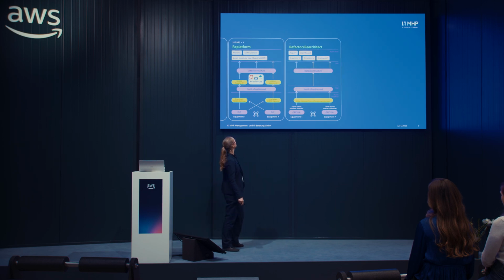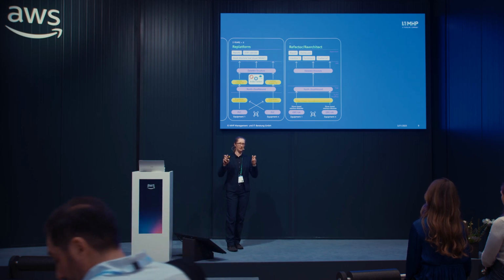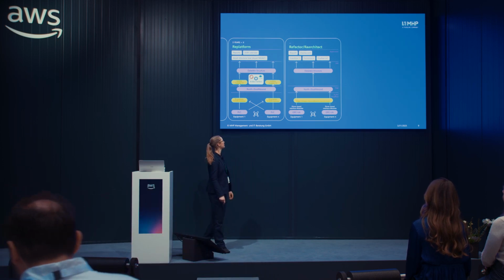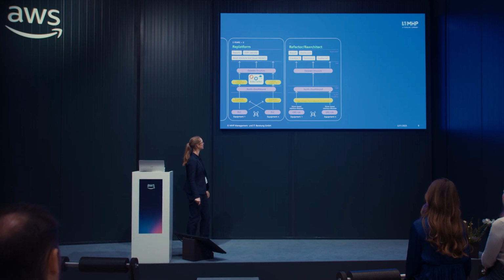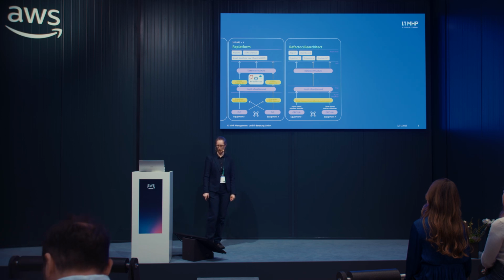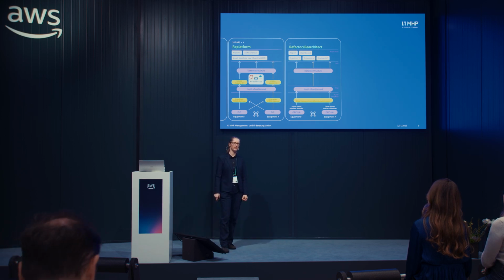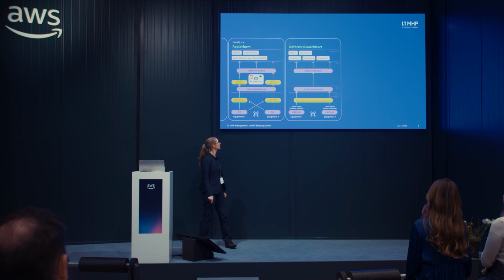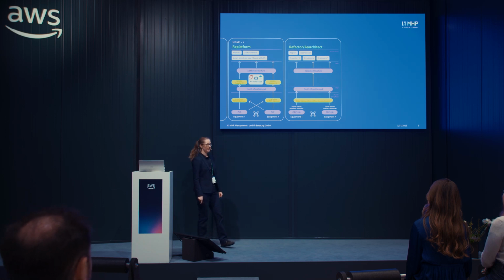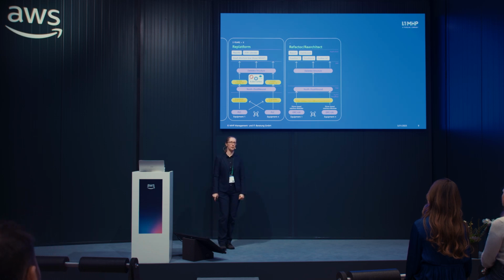So talking about the re-platform step, we basically do the same thing underneath the north and southbound. So we have a still proprietary SCADA gateway which maintains the connection to our shop floor. But now we do not only integrate one SCADA supplier, but different ones. And above the north and southbound connection, we now have a monolithic SCADA system, but embedded in Docker, Kubernetes or OpenShift.